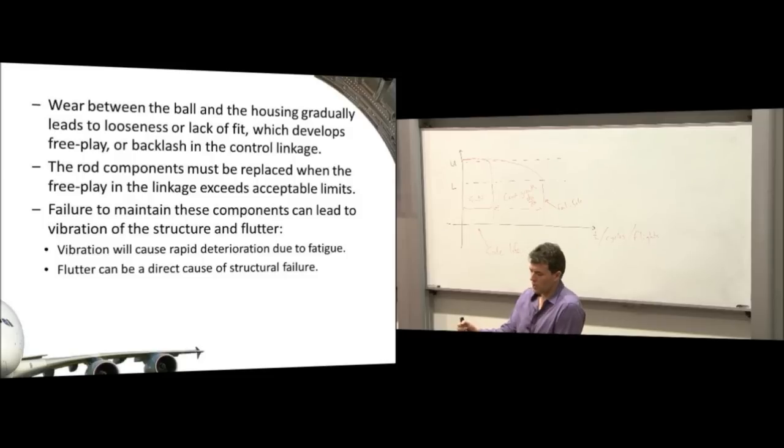So in a small aircraft, if the pilot pulls on the stick, the yoke might go to a push rod, and that might be connected to a cable, and that cable might run through some pulleys and then back to another control linkage that controls the control surface. So there's a lot of connections in that system.